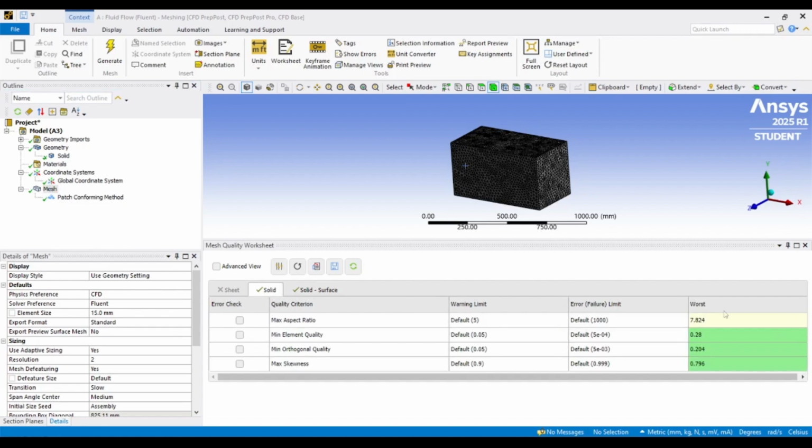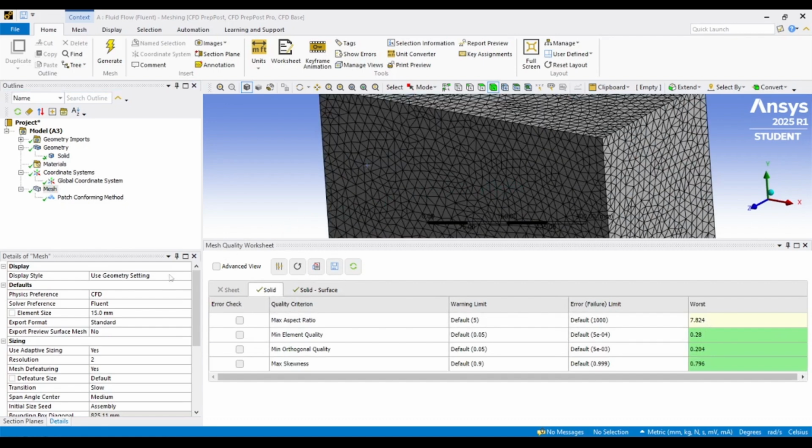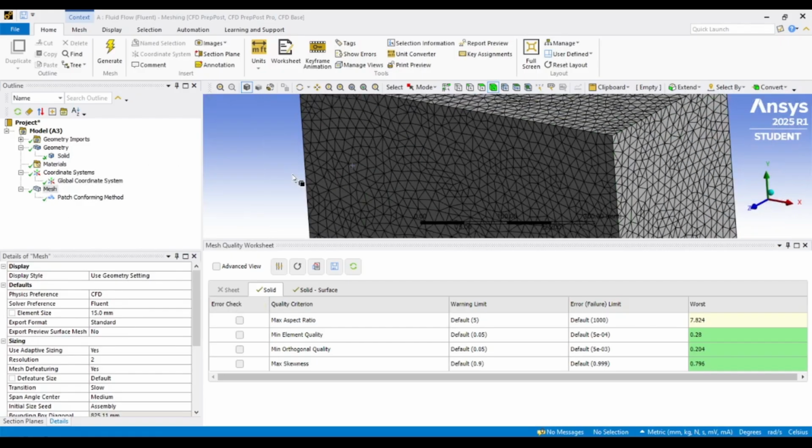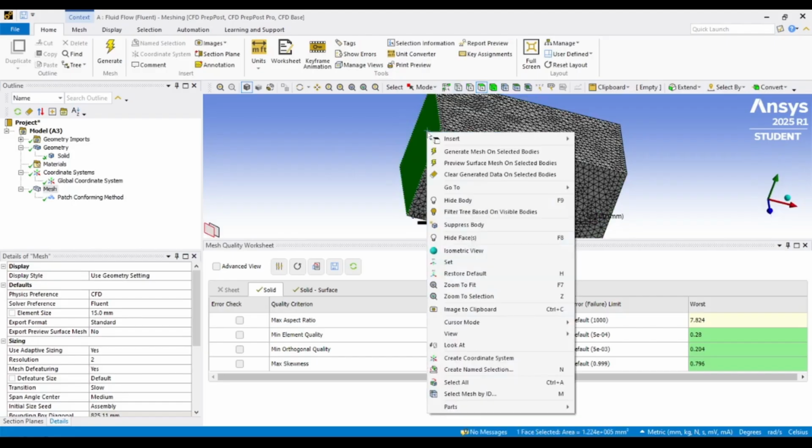approximately 1, followed by a steep drop on the sides and a sudden rise again near the rear stagnation point due to recirculating flow. Comparing this curve for laminar, turbulent, and transient cases will show how turbulence delays separation and reduces drag. Next, analyze the velocity field around the cylinder.